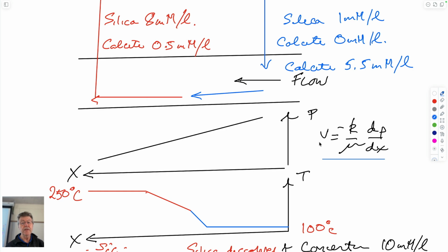We use Darcy's law. We can get the volumetric flow rates defined by the pressure gradient across the reservoir. So if we know the pressure gradient between injection and recovery wells, for either a very simple one-dimensional geometry or a more sophisticated geometry, as we talked about in terms of flow nets, where we could work between equipotentials, we can go like this.